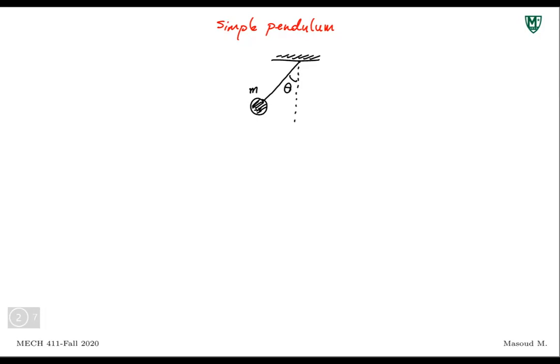Now let's draw the free body diagram and kinetic diagram for this. Again, from dynamics, depending on how much you remember of the equation of motion, free body diagram, and kinetic diagram, or if you were calling it the inertial forces diagram. All right, so I'm going to draw the free body diagram here. I have the mass there. mg is pulling it down, and T is the tension in the string.